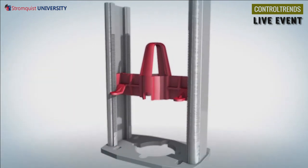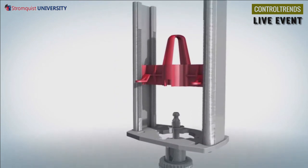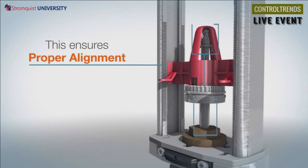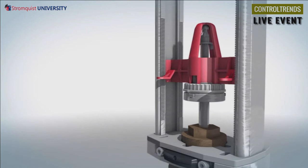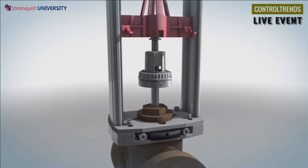Install the linkage riser. Align the red centering device on the linkage riser with the top of the stem adapter. This ensures proper alignment from the valve stem to the actuator stem. Tighten with the provided 4 screws using a 4mm wrench. Discard the centering device.